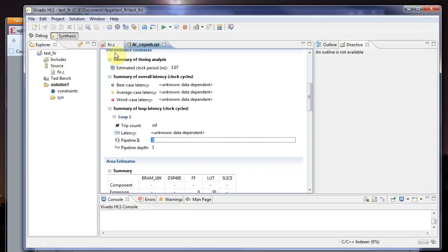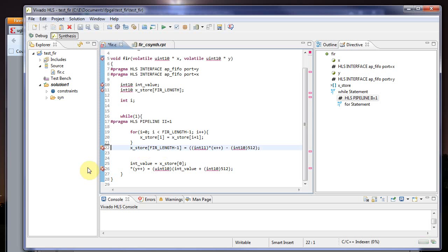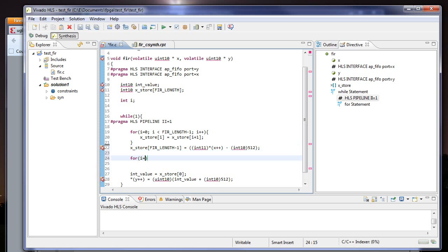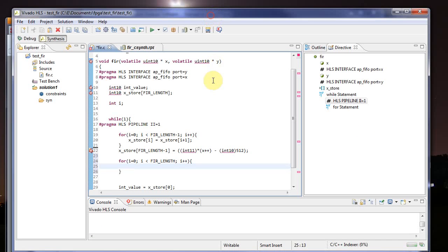And while that's going, let's continue to look at the rest of the FIR filter. So we have data shifting through. The next thing we need to do is actually apply the filter, and that's going to be the actual multiplication of all the filter coefficients. So the same thing, I'm going to loop through. It's worth noting that when I apply this pipeline directive, it's automatically unrolling these loops. There's lots you'll have to read when you actually start doing this. But I don't have to explicitly tell it to unroll all these loops to achieve that pipeline. It'll figure that out.